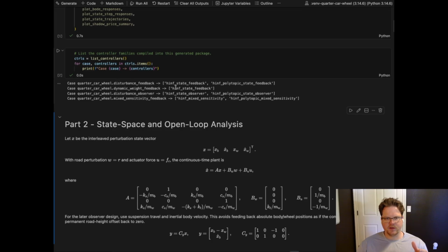I have a dynamic weight feedback, where I'm going to introduce different performance criteria to actually shape the objective criteria of ride comfort. It's a similar notion to the R matrix in optimal control for penalizing control effort, and just different criteria. So you get a little bit of this Pareto optimal frontier kind of objective shaping.